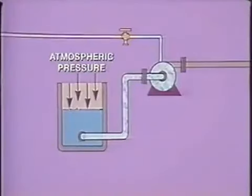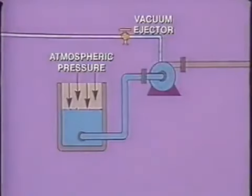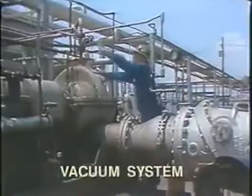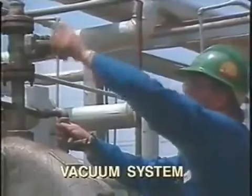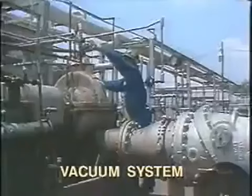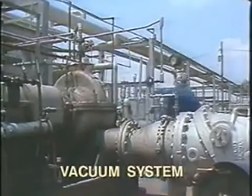If the pump takes its suction from below, the pump can be filled by some sort of vacuum-producing device. As the air or gas is removed from the casing, the liquid will enter as a result of atmospheric pressure. This is similar to drinking through a straw. Many facilities have a central vacuum system which is used for priming pumps. There is a vacuum line connected to the pump discharge line, and to prime the pump, you open the valve on the vacuum system.